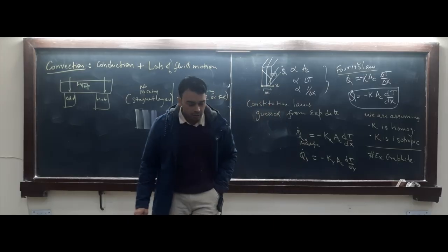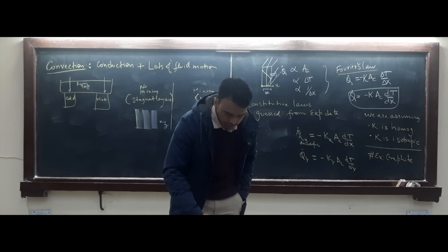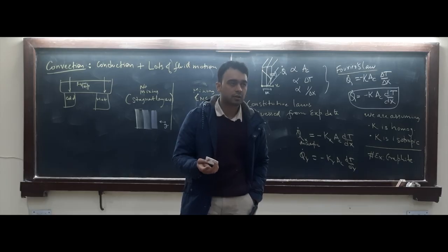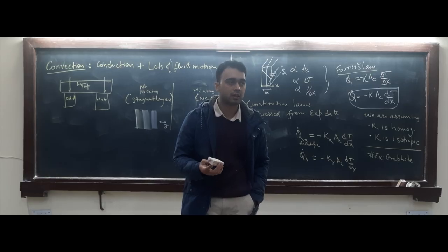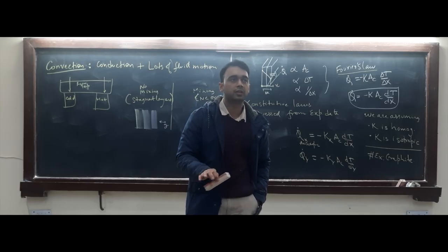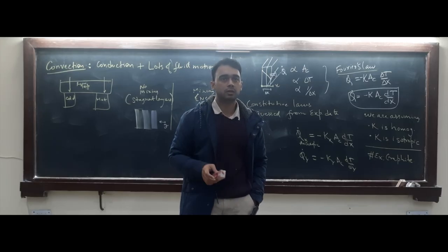With that, in case of forced convection, you do it artificially. In case of natural convection, the fluid naturally mixes due to density differences. A fluid's density increases or decreases with temperature? It decreases, it expands, right? And so naturally you will have a condition where there is lighter fluid on the bottom of the heavier fluid. It will naturally want to come up, and that will induce your mixing.